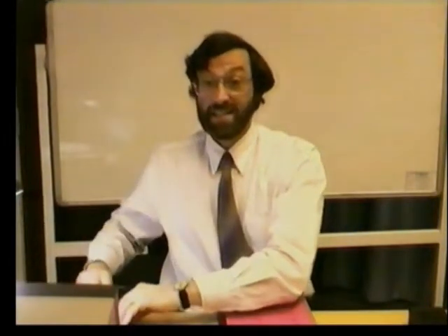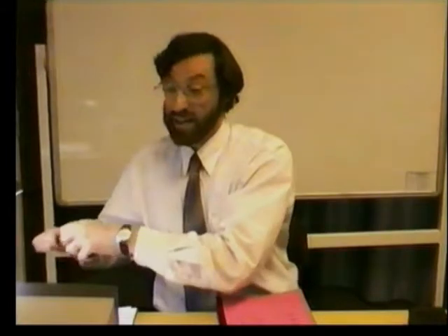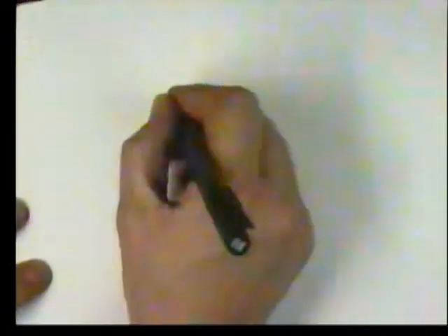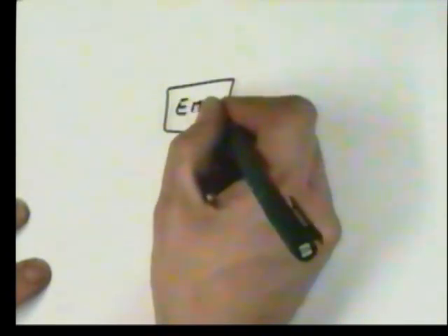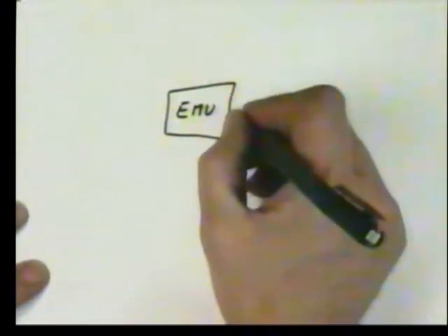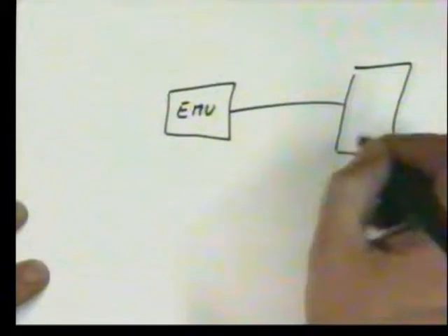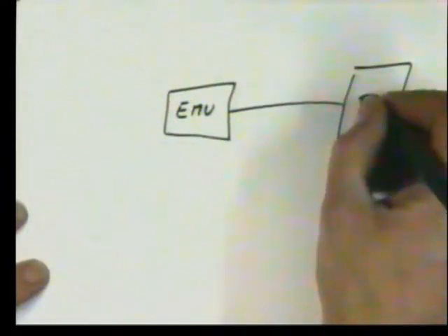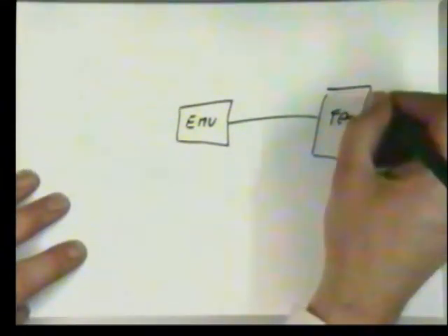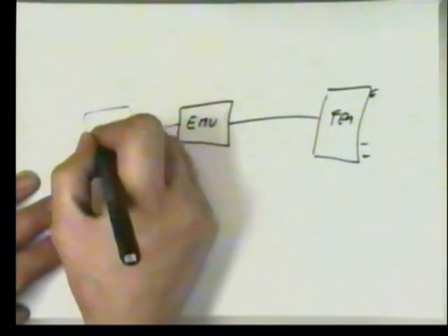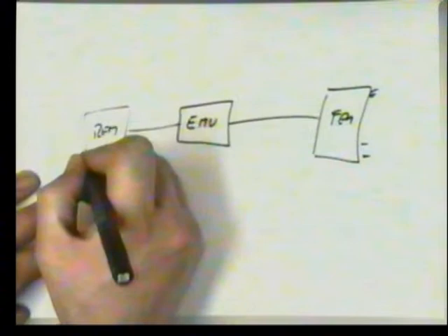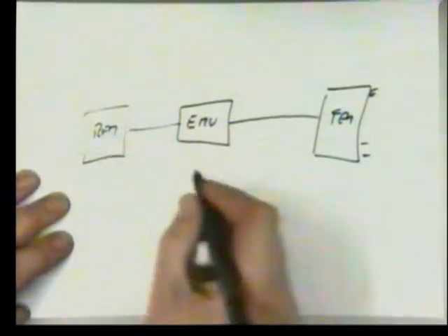You will see instead a distributed local area network within that car, and what you will have somewhere is a central processor, usually the engine management unit. You will have at the front of the vehicle a front end module that's controlling the lights and other sensors. You'll have a rear end module controlling the electrics at the rear, the fuel pump.